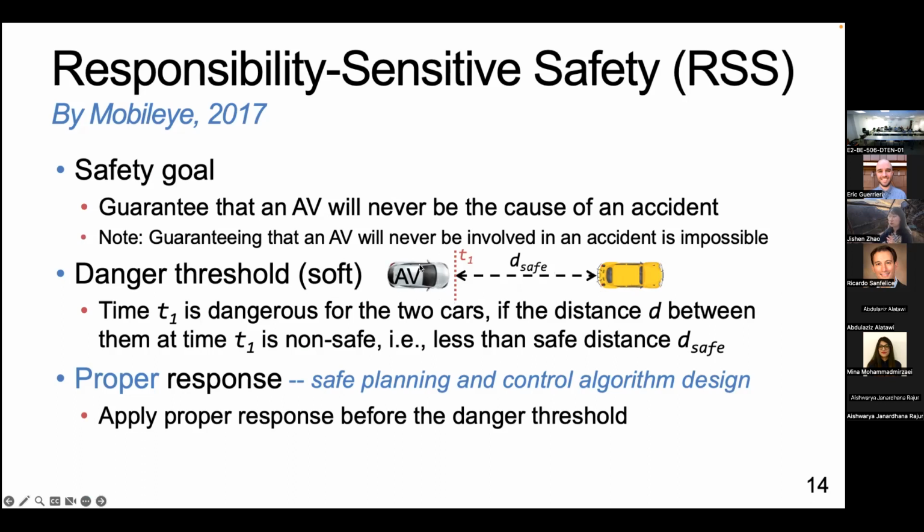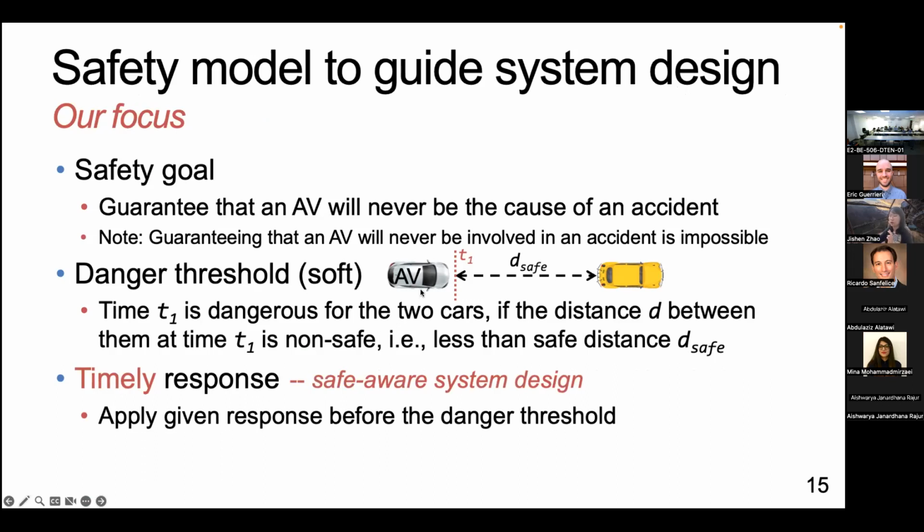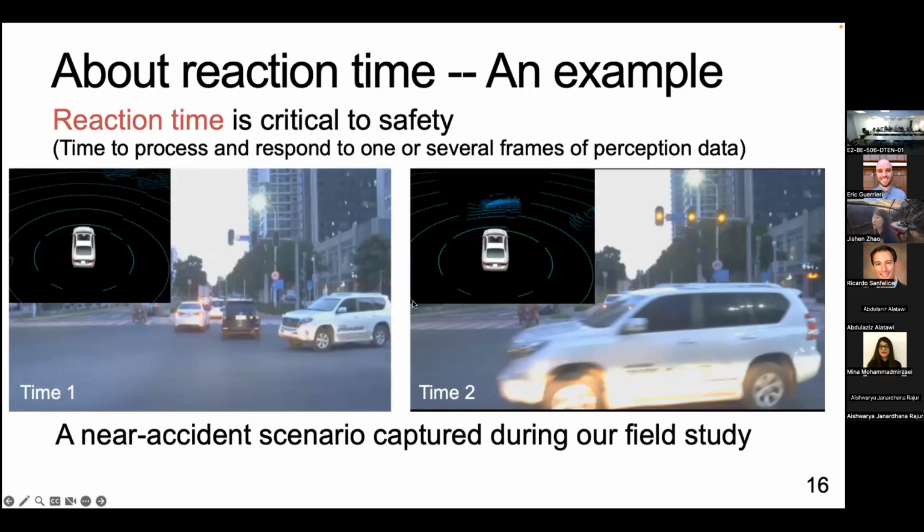But if we think about it, it takes the autonomous driving AV altogether as an agent, and does not provide specific safety requirements for the computer inside it. It focuses on the whole car, but as computer engineers, we want to focus on the computer design specifically. So what we will focus on is how we can map this kind of safe distance requirement to the computer system design, or specifically the latency or response time requirement of the computer system. So this is the main focus and main goal of our computer system design.